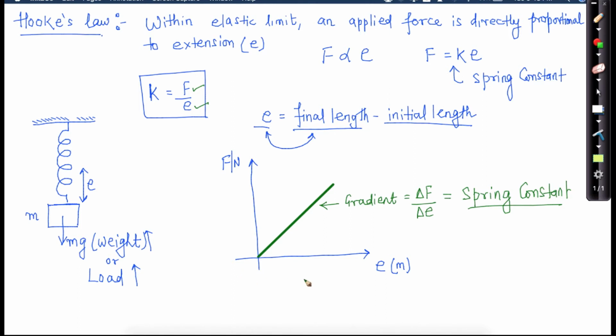Now sometimes in the exam they ask you to show where the elastic limit is. So how can you identify in a particular graph at which point you have an elastic limit? So let's say the graph is like this. This is force, this is extension, this is in, let's say, centimeters, this is in newtons, and our graph is going like this.